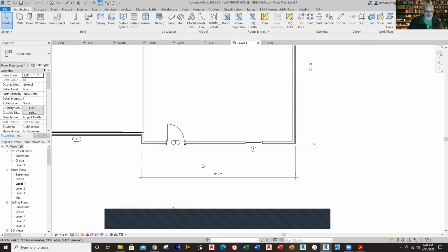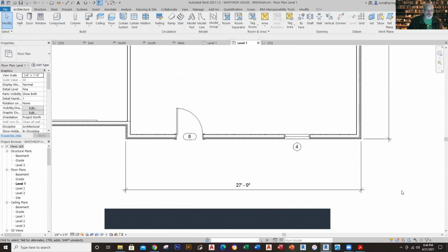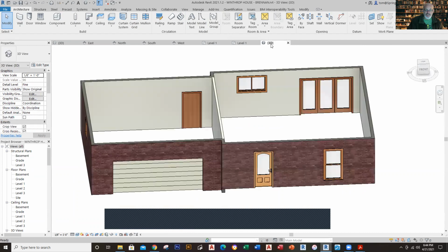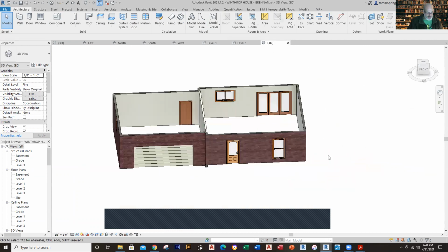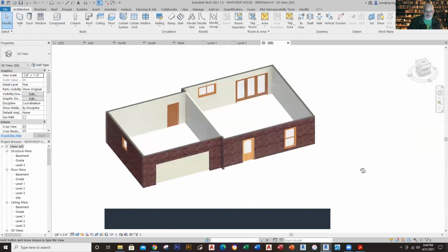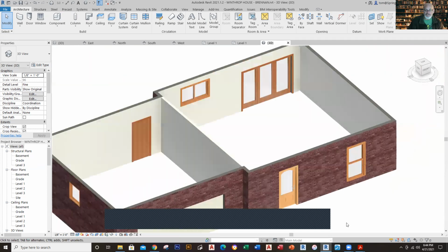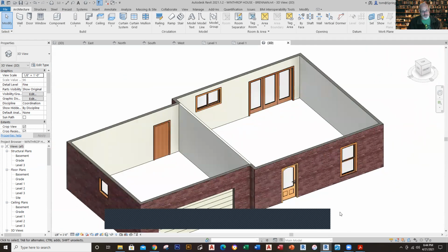We just got to make sure that the temporary dimensions align. So we'll go to there, go to the midpoint, and make that 7 foot 4. So 7 foot 4 like that, and that places that. Okay, so once we've got that in place, we take a look at it, and it looks like this. You've got this going on right there, and then you've got this. That is what you've got happening right there. Okay, so that's basically what we'll take a look at. Now at this point, you can begin to put in your interior walls.